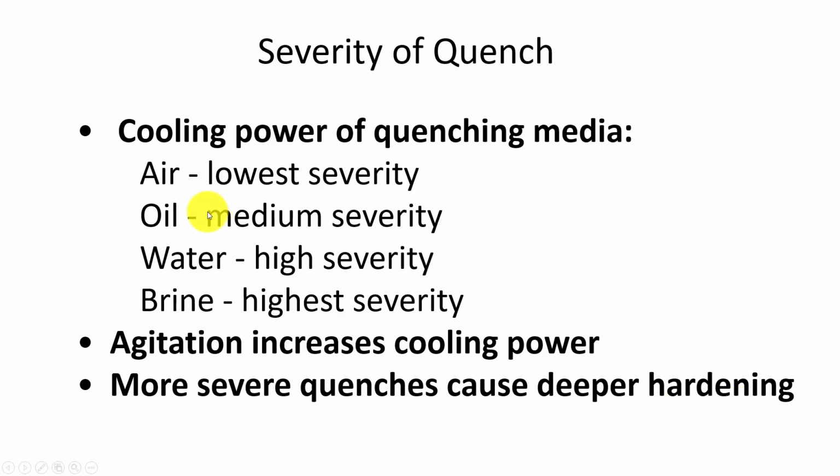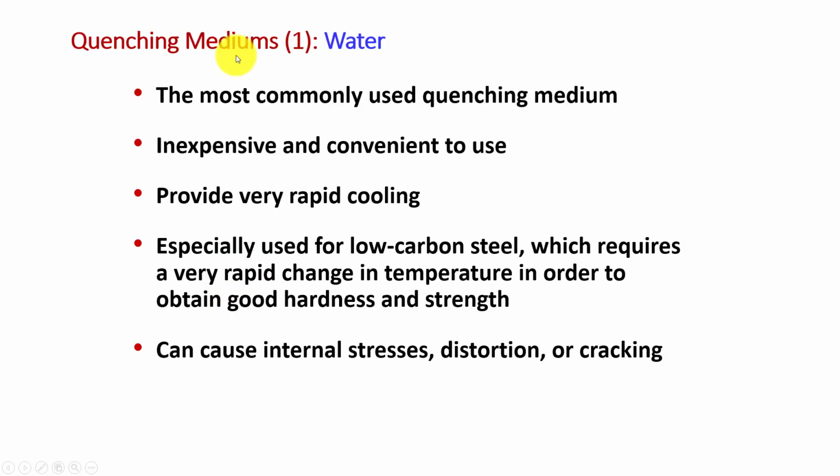So if I want a deeper through hardening effect, I need to probably look at brine or water. Let's talk about these different quenching medias. Water is great because it's very cheap. It's all over. We can dispose of it fairly easy. Again, I say dispose of it.